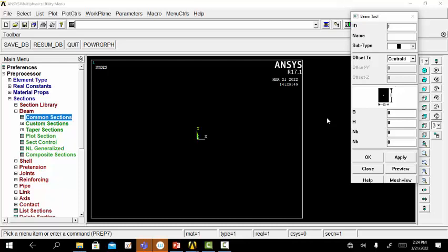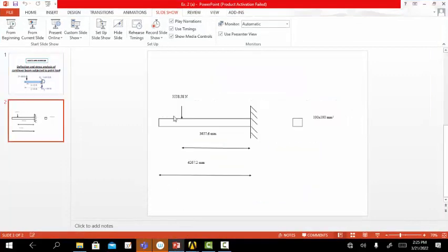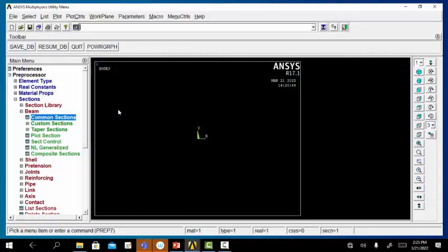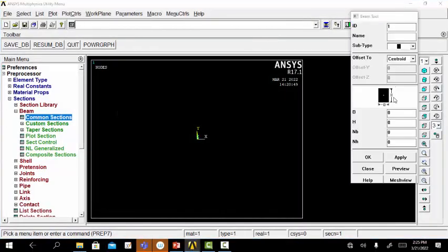Okay, so we have to provide the breadth value as height and height value as breadth in the APDL software. So here in the given problem, both breadth and height, height meaning thickness of the given beam, are the same at 100 millimeters, so there is no problem. Directly we can feed the breadth and height values as inputs.